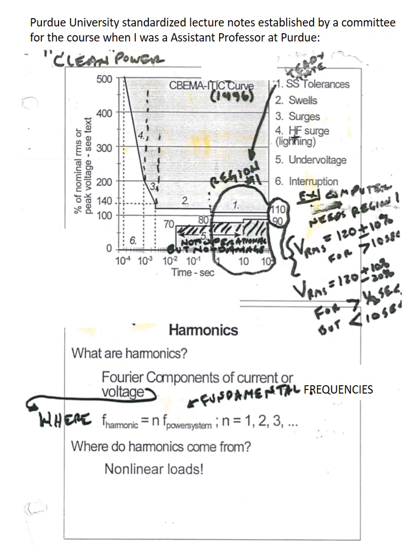What can happen is you have AC power being delivered to your building, to your computer rooms, and then if there's a factory nearby or other sources, generators and things, there's harmonics that can come across the power grid, and waves superimpose on each other, creating problems, right? If you know wave theory, resonant frequencies and things like that. So that's something you have to monitor too, and control, not just monitor, but filter out and mitigate.